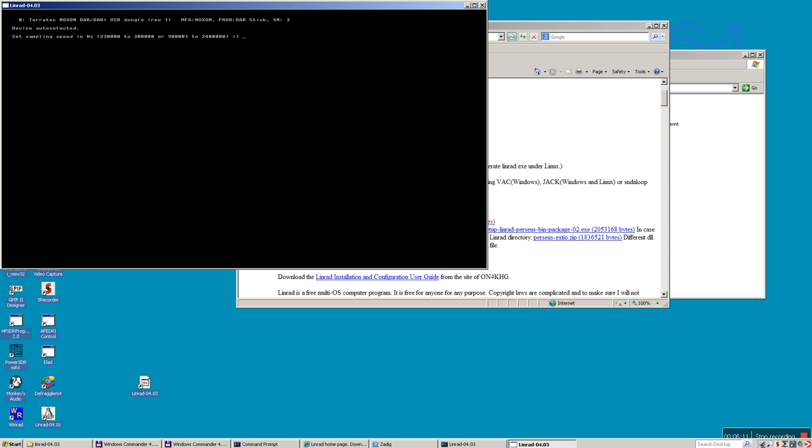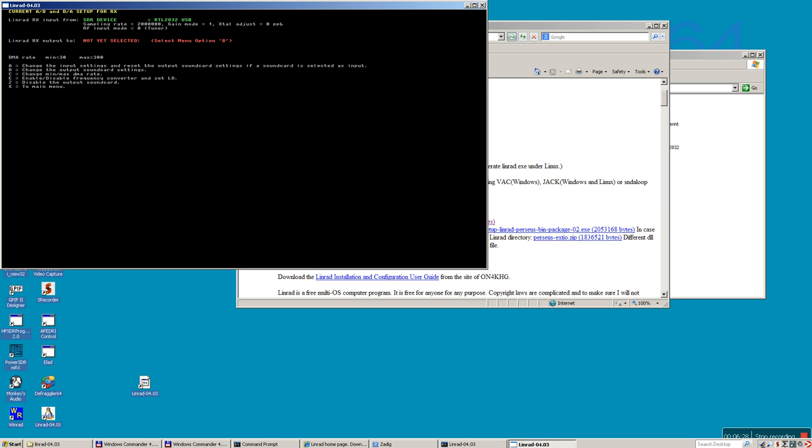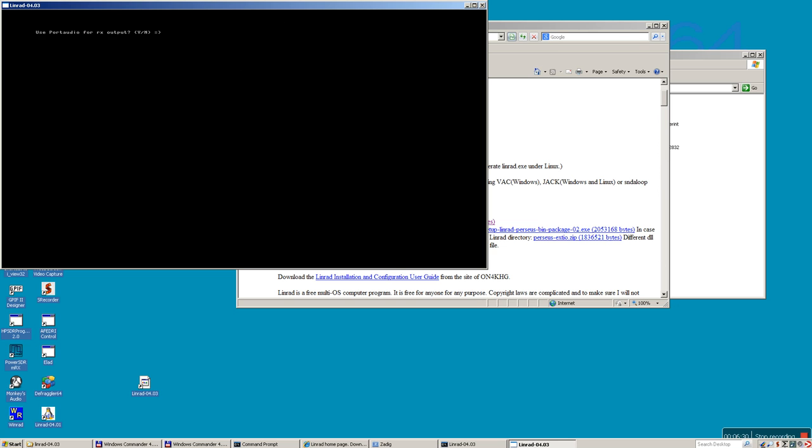I select 2 MHz and the tuner input 0 and the Osmocom constant gain setting and 0 for the frequency correction, and B without PortAudio, and the motherboard sound card, that's A. So sorry, that's 0.